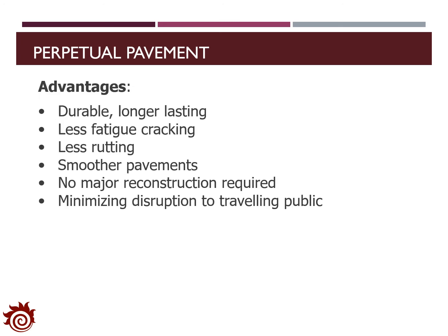There are a lot of advantages of perpetual pavement. First, obviously, the pavement is durable and can last for a longer time. It's designed to work for more than 50 years. And second, the pavement can experience less fatigue, cracking, and rutting based on the design of the 3 layers.